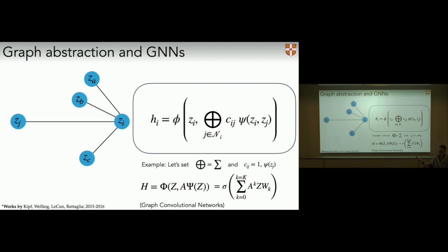And what that allows us to do is we then conveniently write out the system in matrix form. And if you look at this equation here on the right-hand side, you see our nonlinearity, and you can see how this equation inside here, so K is actually the number of communication hops or interaction hops in the robot topology. We have our adjacency matrix, we have our features, and W is simply the set of parameters that we're trying to learn here. So everything is very nicely exposed when we write things down in this matrix form. And so now we know the parameters that we're trying to fit. If at train time we can observe the topology of the interactions, we have all the information that we need to actually tune these systems.